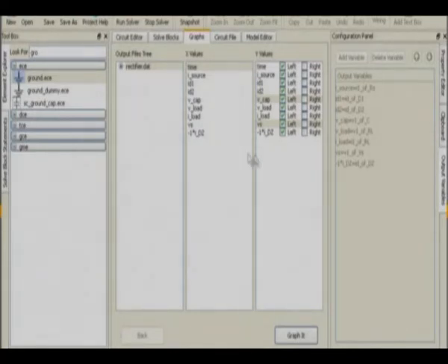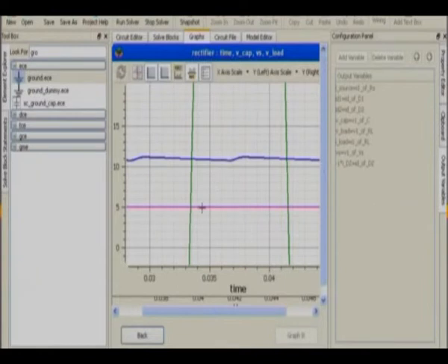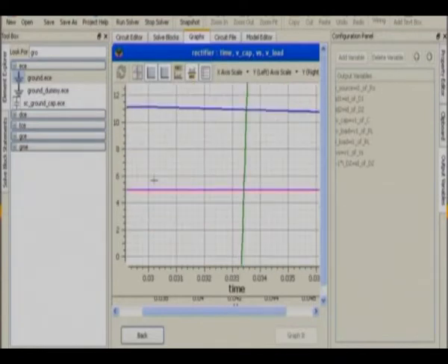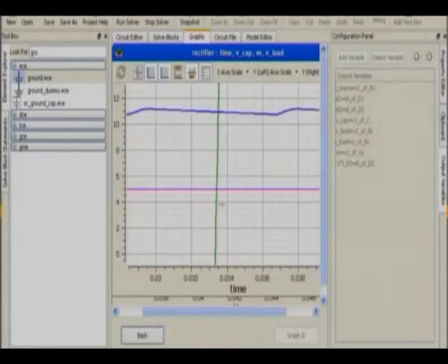Okay, you can also look at the voltage at the load, that is the output voltage, and that is of course regulated. Therefore, it's much better than the capacitor voltage. So that's at 5 volts because it's a 5 volt Zener, and you see the ripple has basically disappeared. Okay. All right. So that's the rectifier example. We'll just look at 2 or maybe 3 more examples, and then we will let you work out things yourself. There is a question.